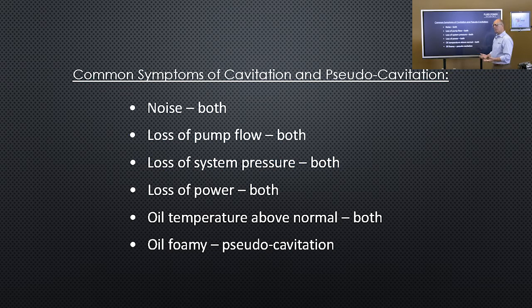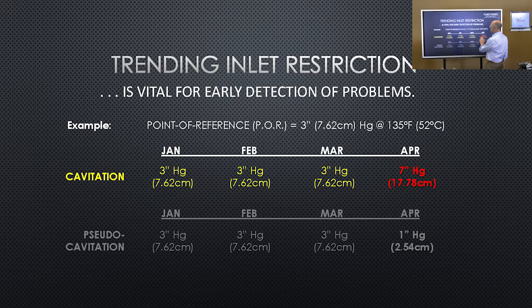The other thing cavitation will do, if it persists, is start to elevate the operating temperature of the oil. And last but not least, if it's pseudocavitation, or if you will, air contamination of the oil, the oil is going to foam. We'll talk about that in just a moment.